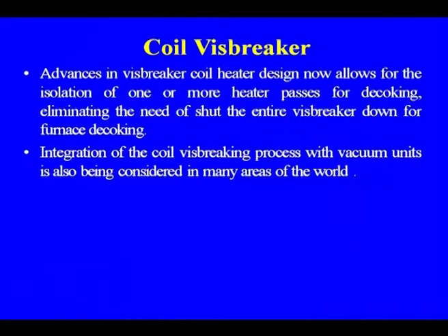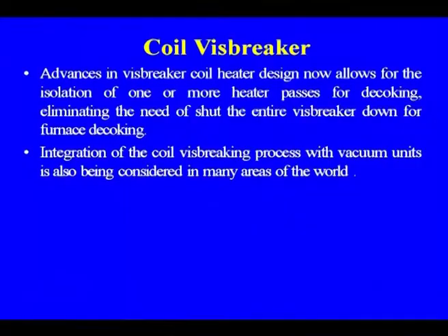Advancing the visbreaker coil heater design now allows for the isolation of one or more heater passes for decoking, because decoking is the removal of the coke during the process. Coke formation will always be there; you can only reduce the amount of coke that is formed, eliminating the need for this shutdown and the entire visbreaker down for the furnace